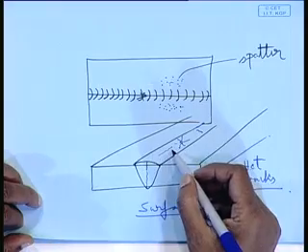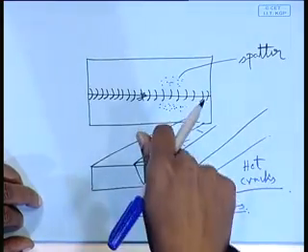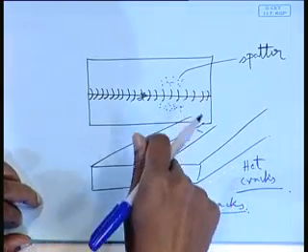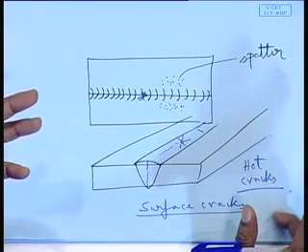So, the tensile stress taking place in the weld metal and the weld metal composition taken together, it cannot sustain that stress and a crack develops. So, what could be the remedy? Well, once the crack has developed, if you have detected it, that has to be scooped out, cut out and re-welded. That is the remedy.